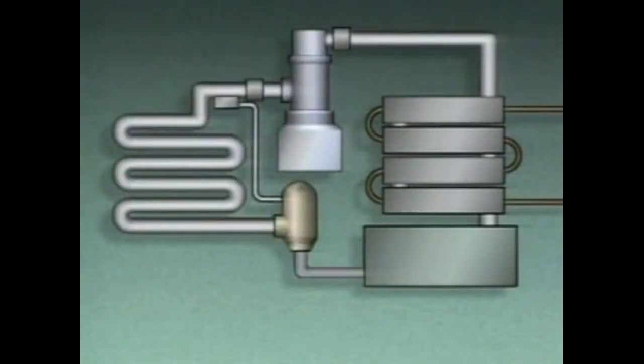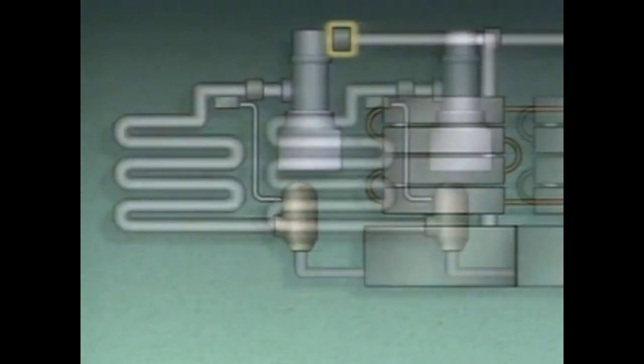As you may recall, the pressure exerted on the refrigerant in the compressor creates the flow through the system. Let's look at a refrigeration system that uses pressure switches to help maintain the proper pressures in the system. This system has a low-pressure cutout switch located on the compressor suction. It also has a high-pressure cutout switch on the compressor discharge.